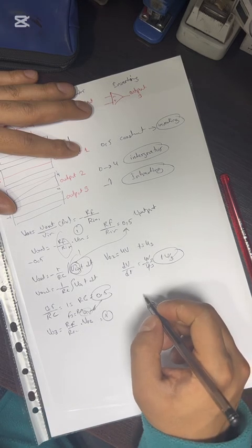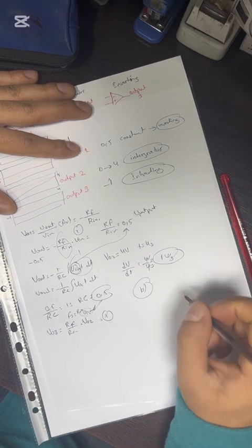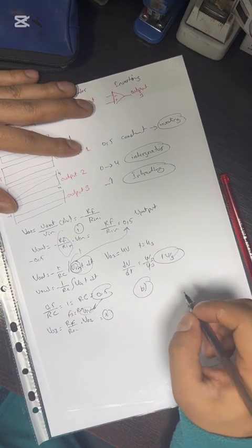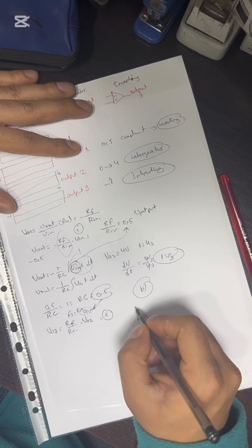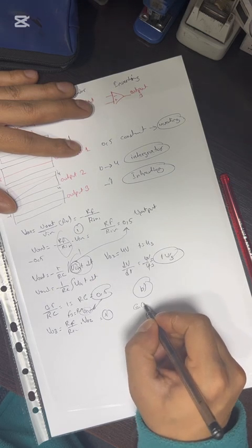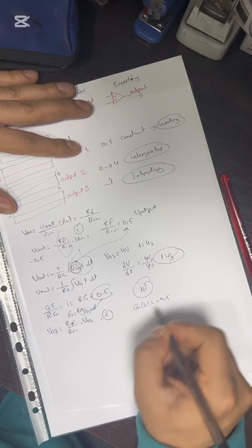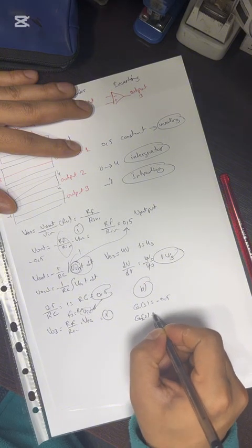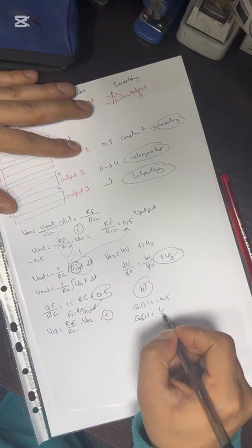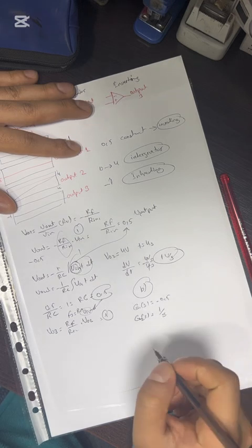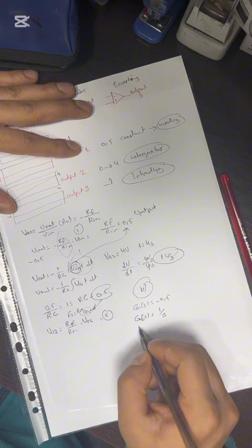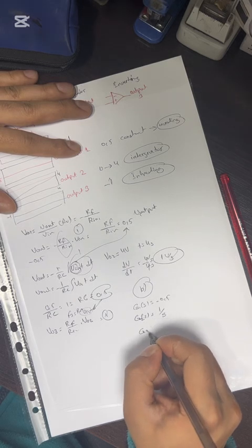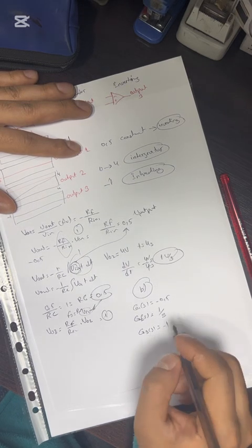So let's start with part B, the parallel connection transfer function. G1 is equal to -0.5, G2 is equal to plus 1 over s, and G3 is equal to -1.